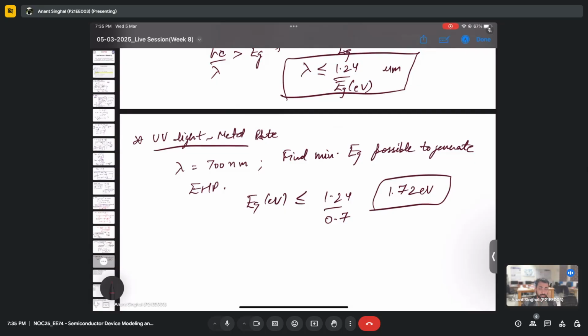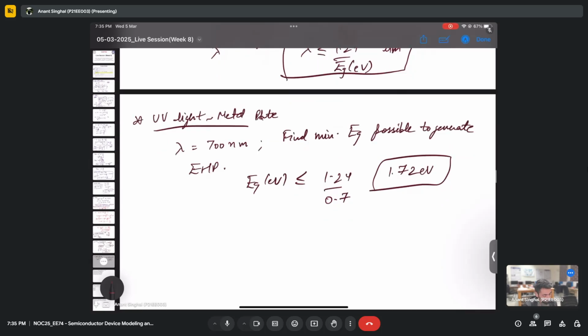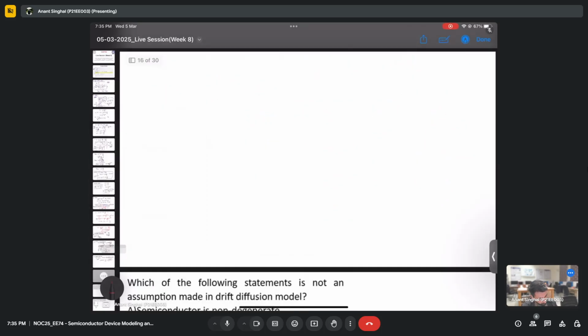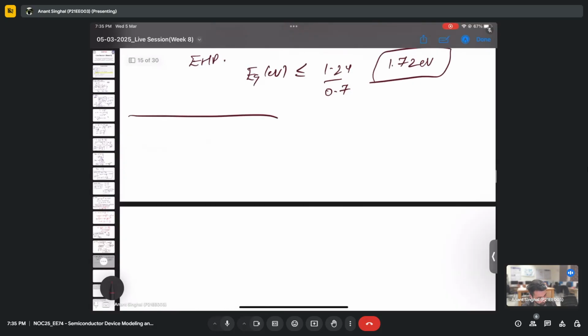Now similarly, as we have the generation, let's say in equilibrium we have np equals ni square, right? Once I dope it, or if I inject some more carriers into it, what will happen? This np will become greater than ni square, because we have more doping. Either n will increase or p will increase, and this does not hold because we are not in equilibrium now.